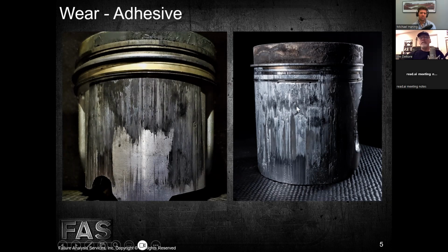And the problem that this creates is not only are we dropping this aluminum into the pan and it can flow through the lubrication system, some of it gets past the filter, it does bearing damage and other damage. But as you can see on this 3600 piston, as these aluminum pieces come off, they start to get up into the ring assembly here. So this is what we refer to as our gross oil control ring. That ring is stuck effectively because of this debris, so we can no longer control oil. So now it starts to get up past this ring here, which is our fine oil control ring, and up into the compression ring, which means we start to potentially burn oil in the combustion chamber, which is no bueno. We don't want to do that.